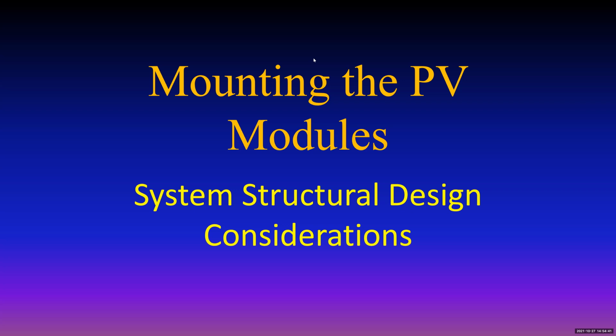The number between junction box and inverter depends on the number of strings attached to the junction box. A typical inverter will accommodate up to 4 strings at the input. We're talking now about the optimizer type system as opposed to the microinverter string. But same thing with the microinverters, it's a matter of how many wires are between the junction box and the combiner box, where it combines the outputs of all of the microinverter strings into a single output that goes to the utility interconnection.